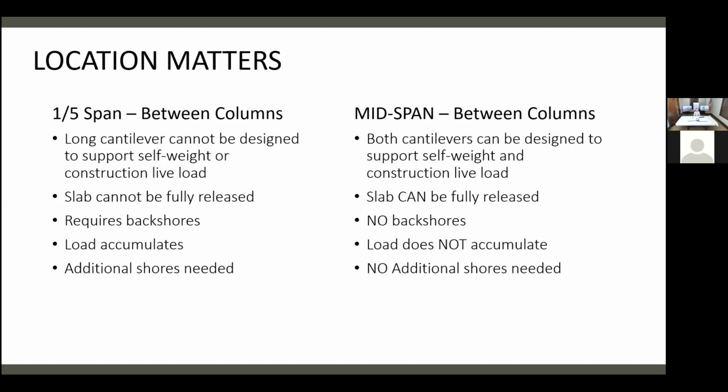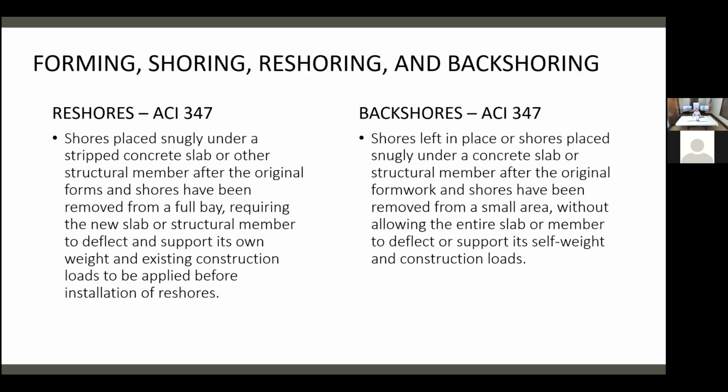At this location, shear is high, moment demand is very low, zero at an inflection point. Otherwise, you're going to put it at a mid-span location. Mid-span, that's where your moment demand is high, but your shear is low. There are certain aspects of both of these that are advantageous for engineering and for building, and we'll talk about those a little bit here.